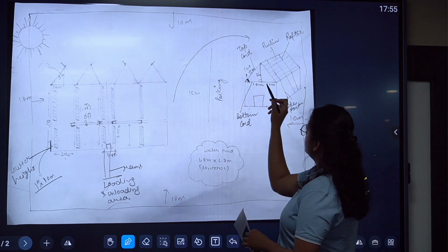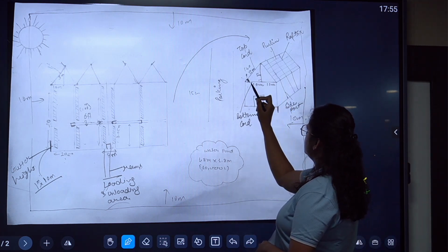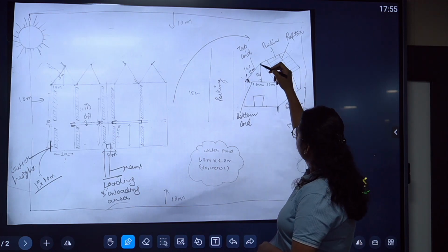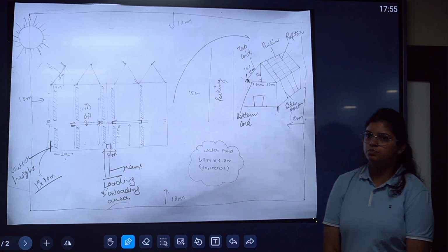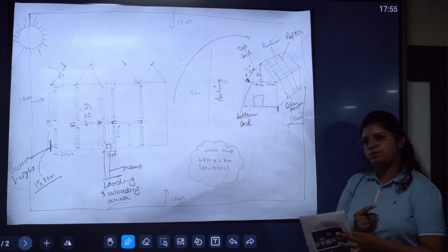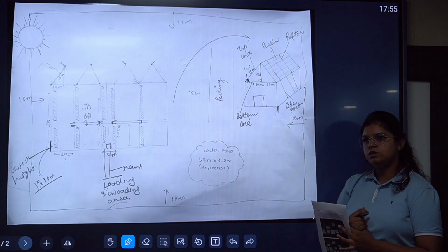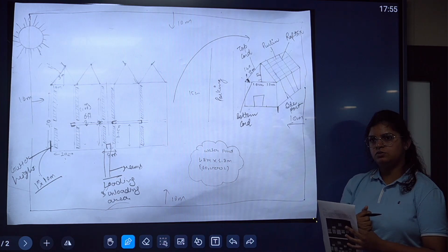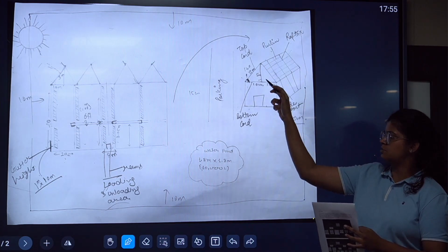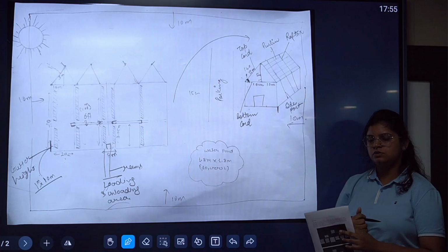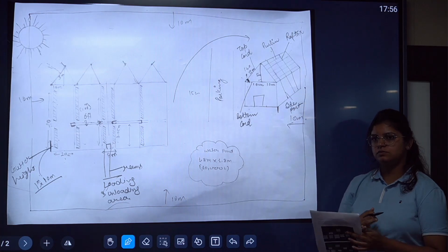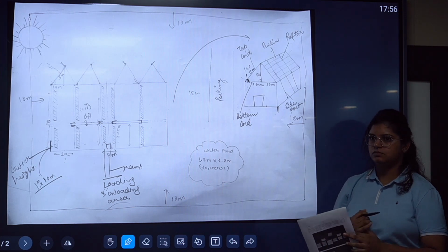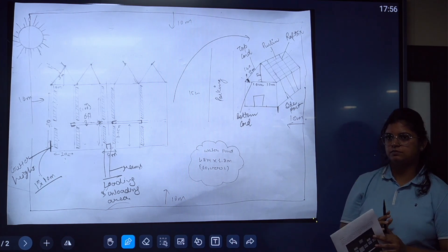So, sir, the query was that we can identify this base length, because this is similar to the base one. How can we identify how tall or how much height we have to take to make this? 6:12, right? I gave you that roof pitch. So, simply, sir, we divide it by half. So it should be twice, right? So you have it right, the 10 meters and 5 meters. Ideal would be something like 12 by 6, but that's okay. We're pretty close then, right? 2:1 ratio. But 6:12 is the right pitch we recommend.